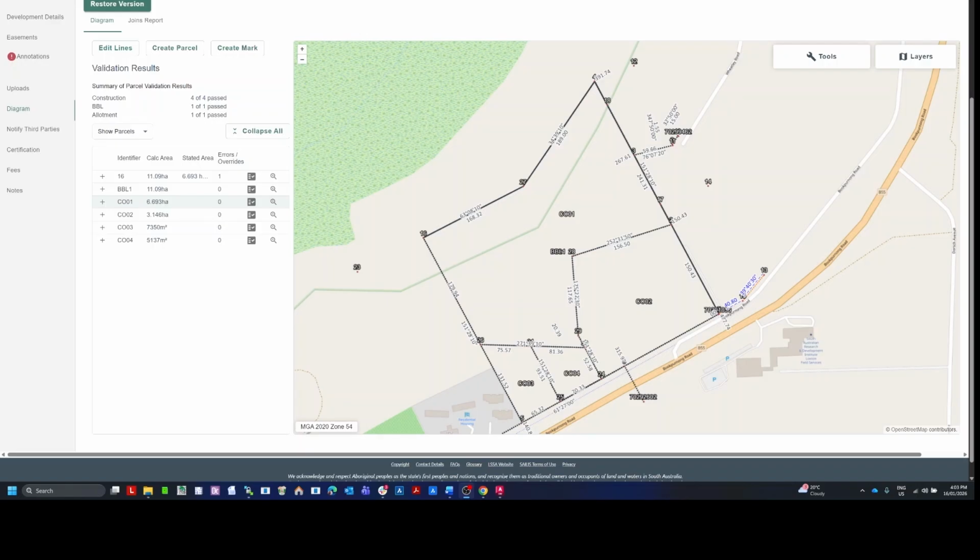When parcel lines for allotments and lots are not on the L parcel layers, then the parcels created are usually the wrong parcel type. In this example, the parcel lines were placed on the L abut layer, and therefore construction parcels have been created instead of allotment parcels. We have 4 construction parcels in this example.